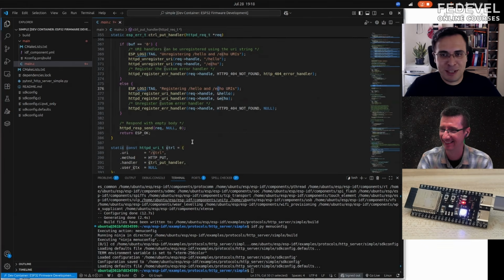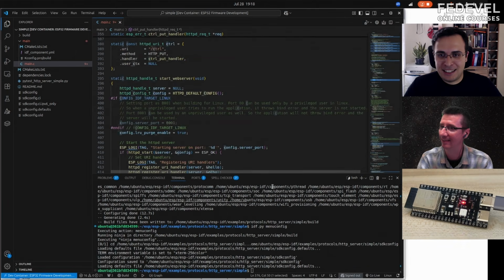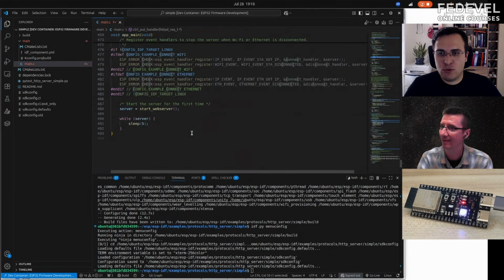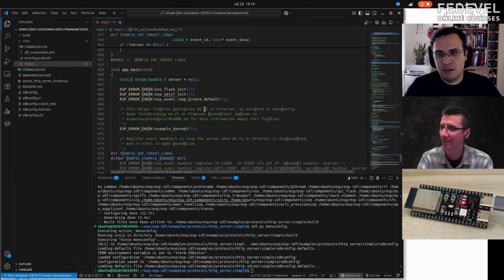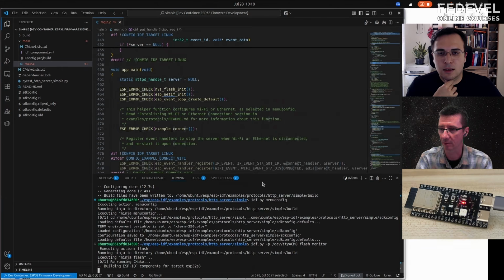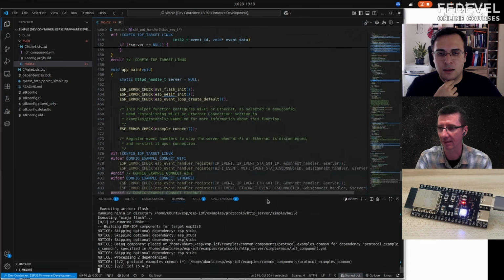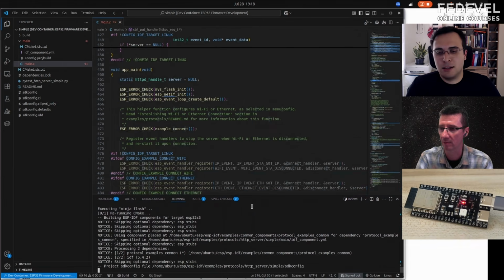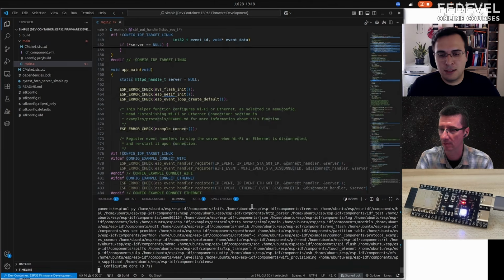It is Zoom behavior. And that should be it, I guess. So we try to run the web server first, and then if we want, we can also change it to control the LED. So idf.py, specify the port, which is /dev/ttyACM0 and flash monitor. Can you also use arrows up or down here to easily repeat the commands? Oh yes, normally you can. Yeah, it is a Linux shell.